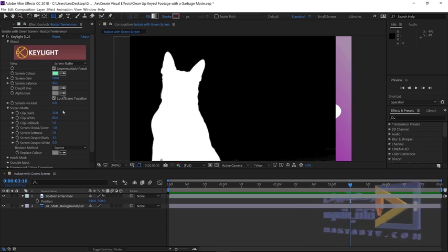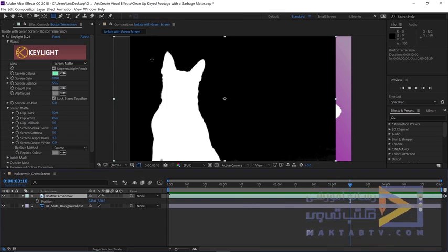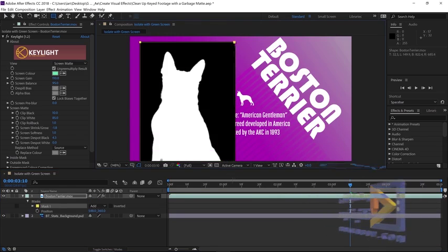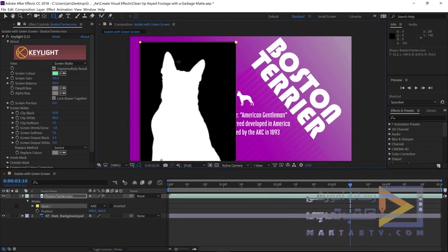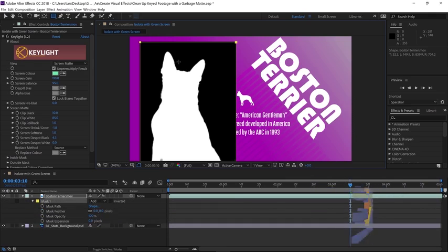Then come down to the timeline and make sure layer 1 is selected, and then we can just draw a rectangle starting in the upper left corner down past the lower right. And you want to give a little extra space so you don't accidentally cut off the edges. Press MM on your keyboard, and if you didn't press it fast enough, it may hide everything. So I'll do it one more time, MM. There we go. That will open up the mask feather options.